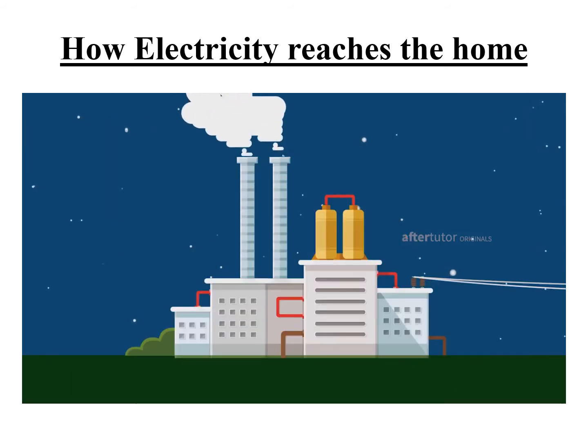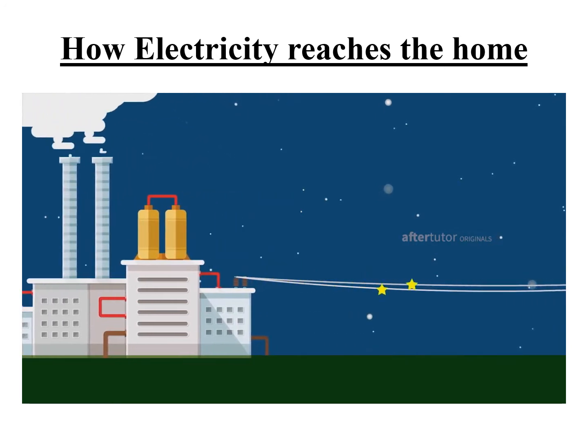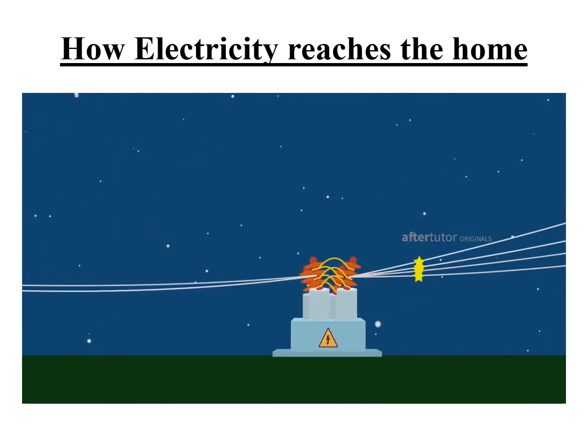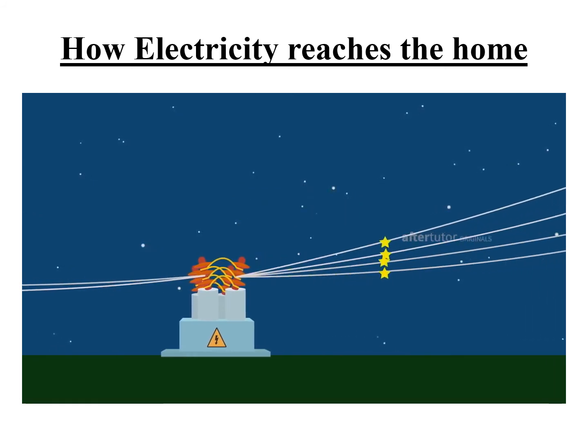It all starts from the power station, which gives a voltage of 20 kilovolts. Houses, power plants, sources of various types. But to transmit this voltage over longer distances, it will be stepped up by means of step-up transformers. That is, the voltage is being increased to reduce the loss of this voltage in transmission.